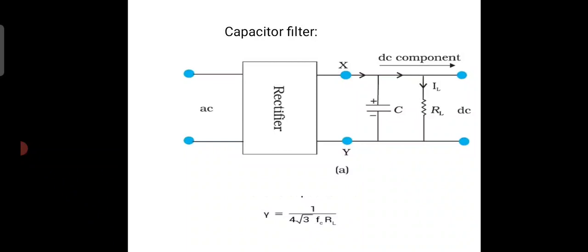Therefore there will be a balancing between the positive pulse and negative pulse. Thus the variation of voltage is compensated by the capacitor. This cycle repeats, but the DC signal is not allowed through the capacitor. Only AC signals make the capacitor charge and discharge.